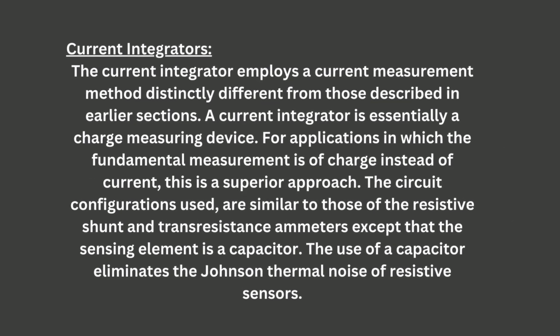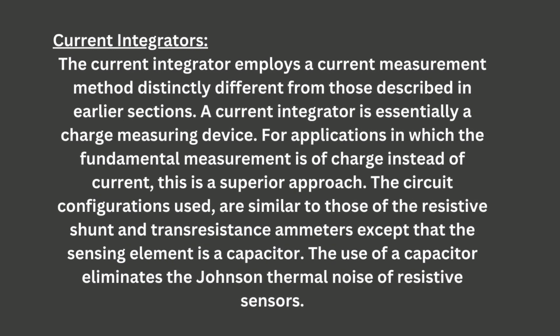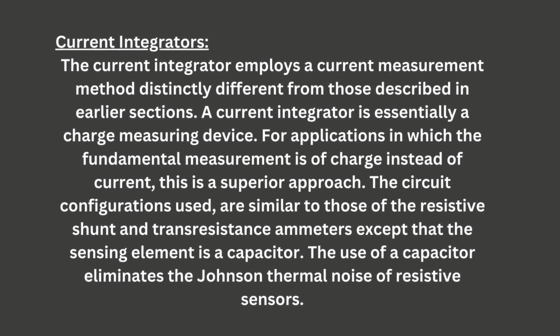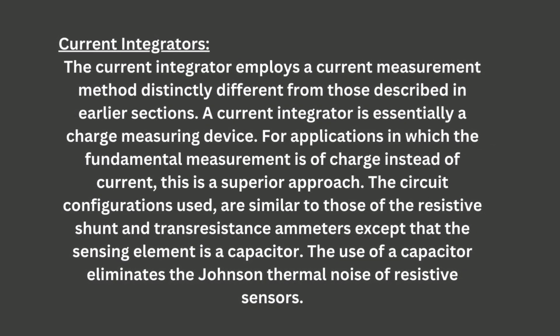Now, let's see about the current integrators. It employs a current measurement method distinctly different from those described in earlier sections. A current integrator is essentially a charge measuring device. For applications in which the fundamental measurement is of charge instead of the current, this is a superior approach.